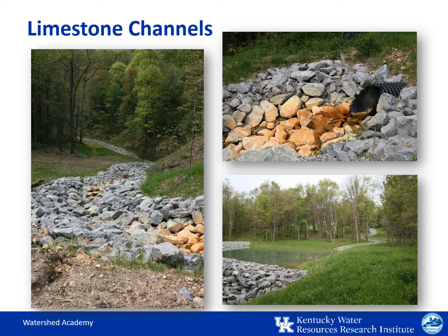When this happens, the rocks can be mixed around or more limestone can be added to the channel. If the channel is on a steep slope, this armoring or crusting may be less likely, but the treatment may be less effective as the water moves over the limestone more quickly due to the slope.